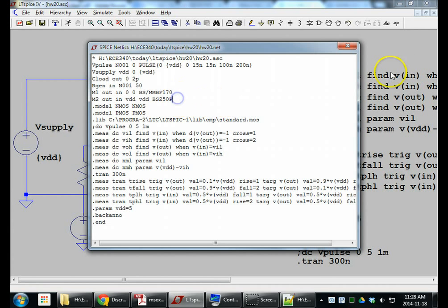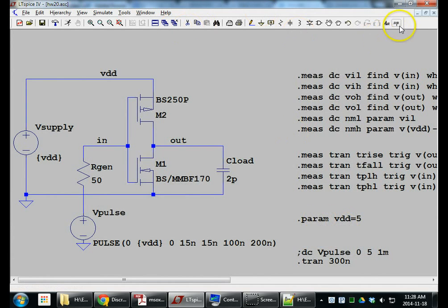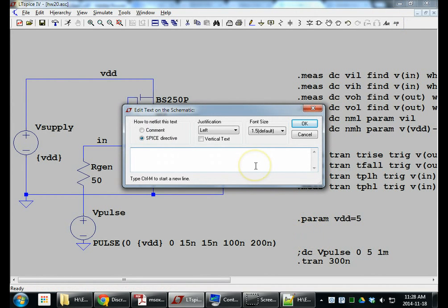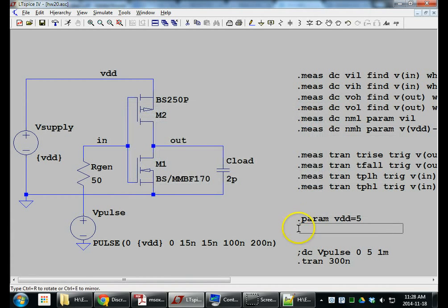How do we do that? Well, first of all, we need to get these definitions in here. We need to include an include statement. Let's do that. .inc vet models.txt. So now we have them included in here. I like these all lined up, a little OCD about that, and then I don't lose things on the schematic. So save this. Can we run it again?